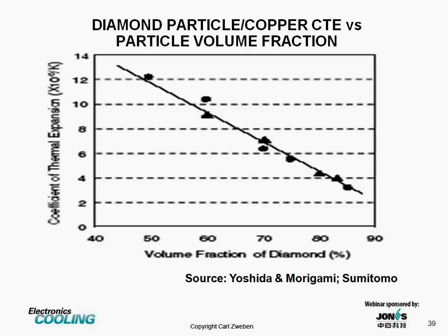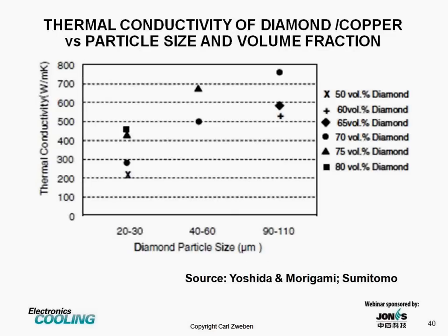Turning to diamond particles, this chart shows the coefficient of thermal expansion of diamond particle reinforced copper as a function of particle volume fraction. And you can see that you can tailor the coefficient of thermal expansion by selecting the particle volume fraction.